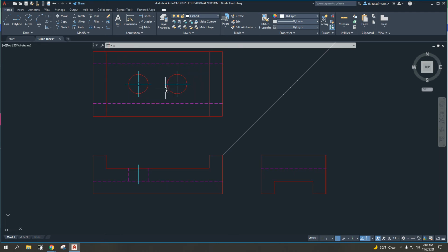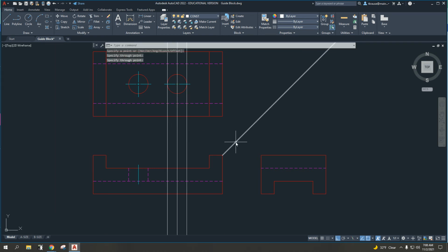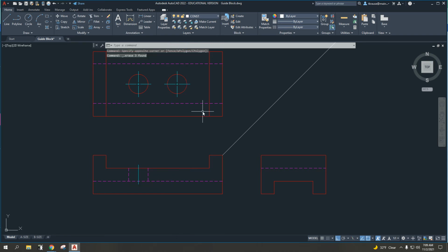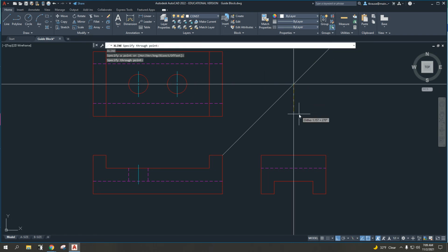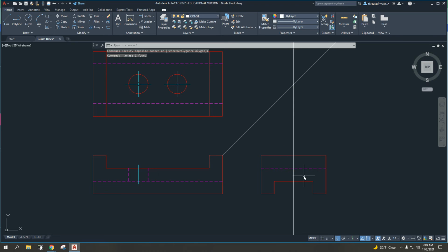And I could certainly do the same thing with a construction line, right? I can do a construction line to do the same concept, okay? And trim this one up. Okay, so I could do the same thing and create those lines. The struggle people will come up with is, well, I'm gonna have to do some math to figure out where this is at, or again, I can use that 45-degree line that we created to find the center of the object. So if you're paying attention, a couple different ways we can draw just lines straight down and trim. We can do construction lines and project and trim those as necessary. But I only need to really do that on one circle, okay?